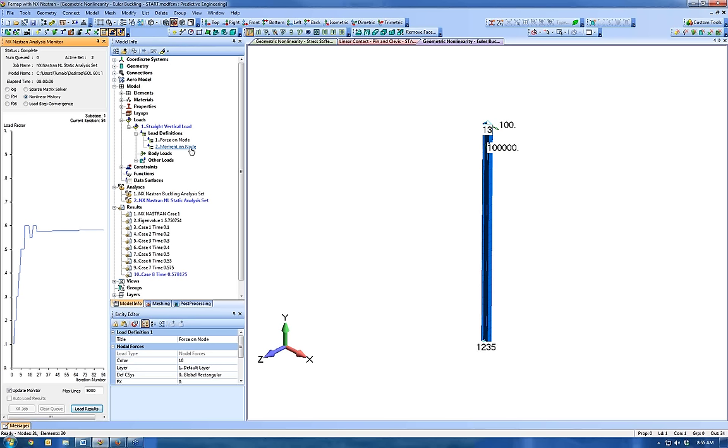You get to a certain point, it doesn't have a huge effect on the results even if you increase this moment load. But you want to be aware, or you want to check your reaction forces and keep an eye on your buckling load, because if I apply 10,000 inch-pounds of moment here, I might actually be a bit overly conservative because I'm putting more bending in this beam than I really need just to instigate the buckling.